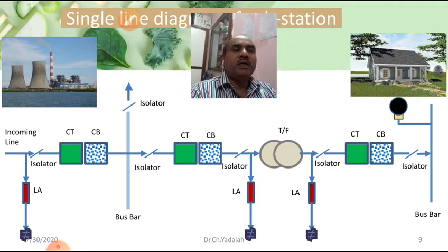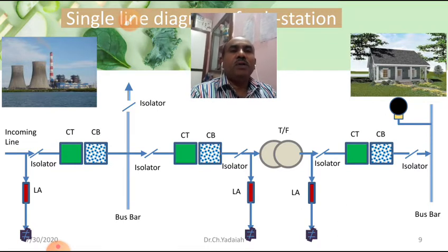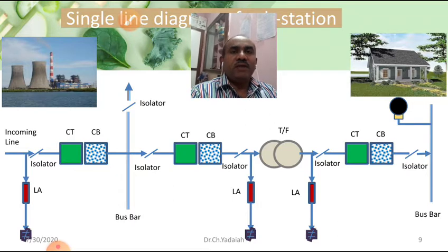How is this energy transmitted to the nearby Warangal substation, that is the 220 kV substation Mulugu road. From that it goes to the 132 kV Veddapalli substation, stepped down to 33 kV, and the 33 kV substation is once again stepped down at REC Warangal substation, where there is a 33 kV by 11 kV feeder. From that 11 kV feeder it comes to the circuit house road, where we have one distribution transformer. Then we step down to 400 volts three phase, 230 volts single phase.